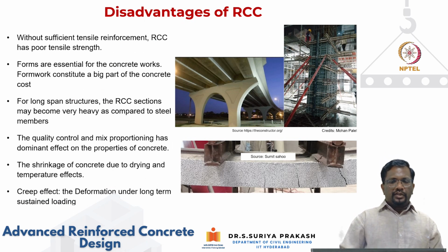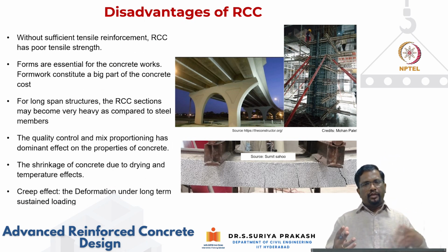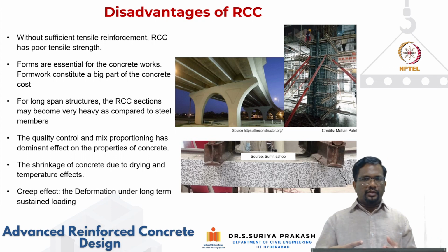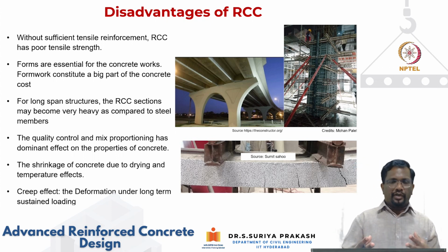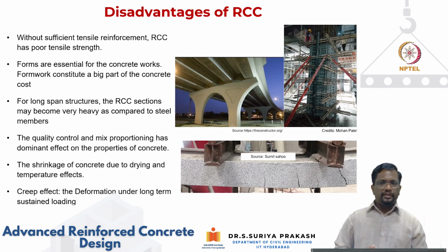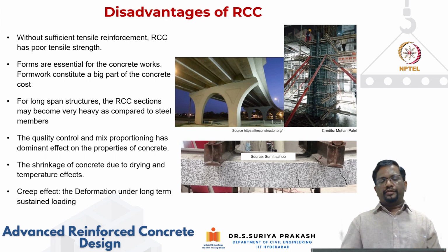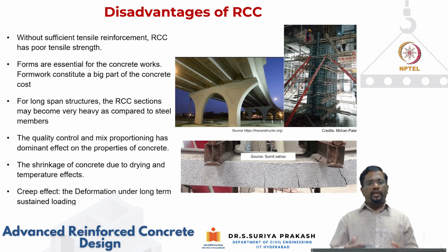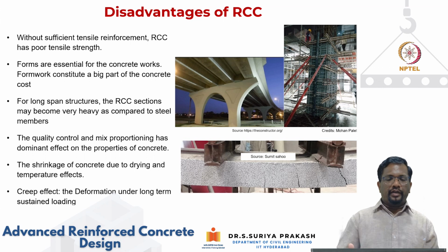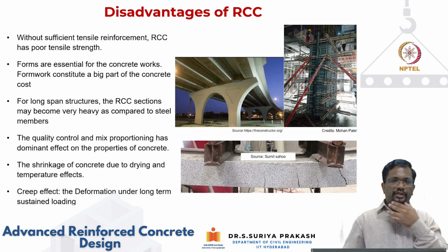Right. Now, disadvantages, of course. Any material will have advantages as well as disadvantages. So, depending upon the requirement, you have to choose a material, right? RCC, again, we know that concrete has very good compressive strength but poor tensile strength. So we have to design the reinforcement. If your tensile reinforcement is not designed properly, it can lead to brittle failures if you're not careful enough, and it can lead to cracking and serviceability issues and so on.